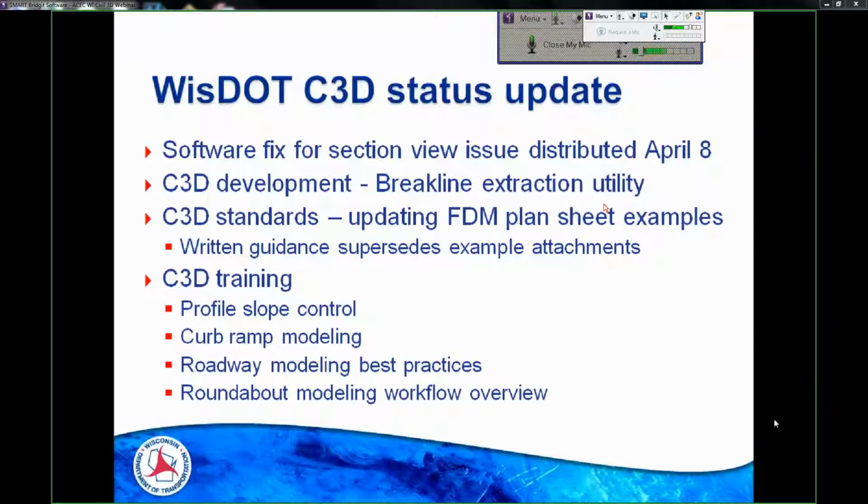It does the same thing if you were adding feature lines or 3D polys as break lines. It grabs those things. At the end of it, you should have a completed break line file. Now, because of the design process, some of those break lines might be obsolete and no longer part of the surface definition. So then that macro goes through and it does a verification process.